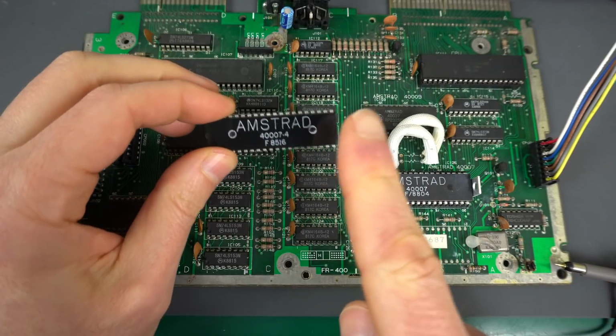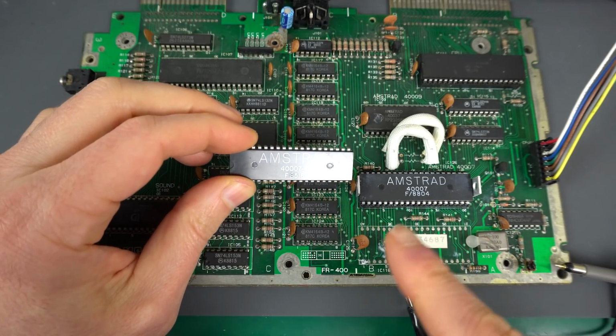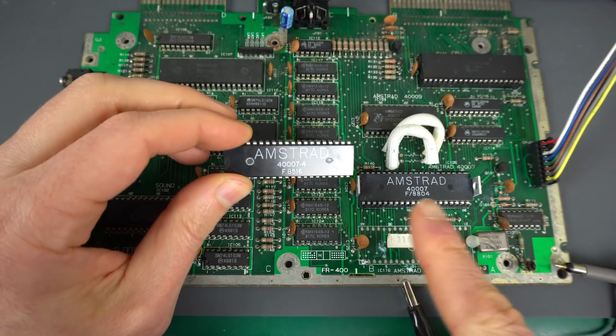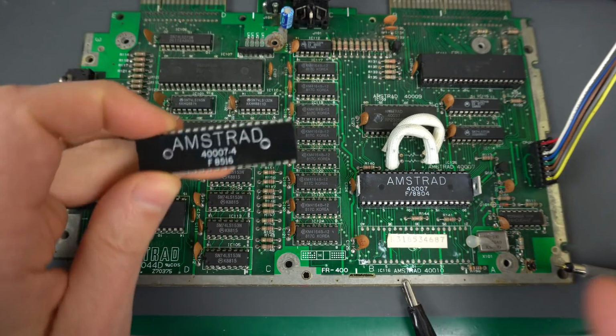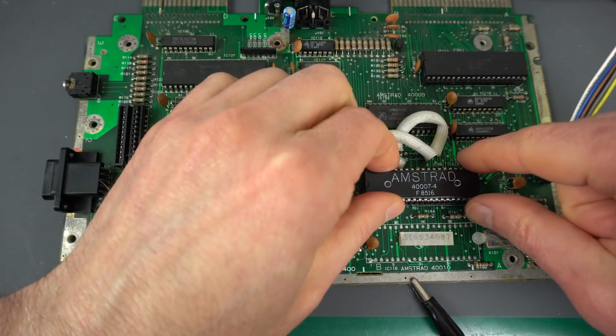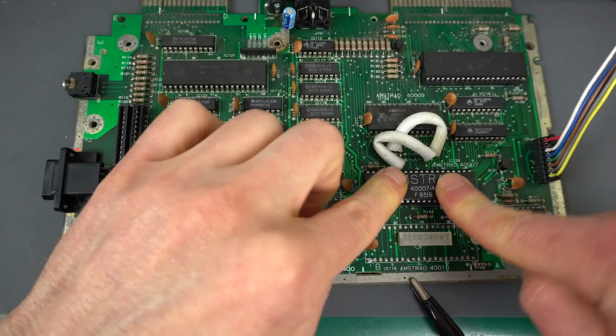Since I have a spare gate array of the same type, I'm just going to swap it out and see if anything changes. It could be that it's both the gate array and the CRT controller. It'd be weird, but it's possible. Yeah, we'll definitely get a lot of questions answered once we try the new gate array.